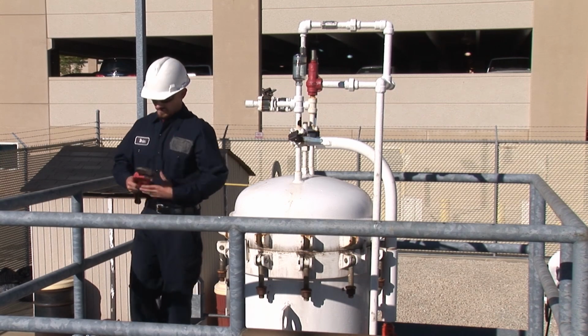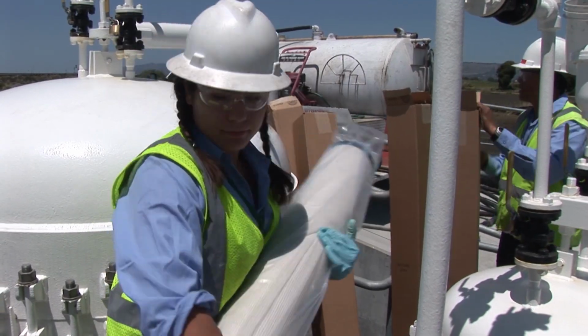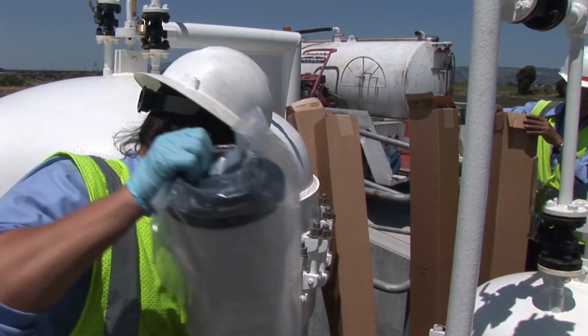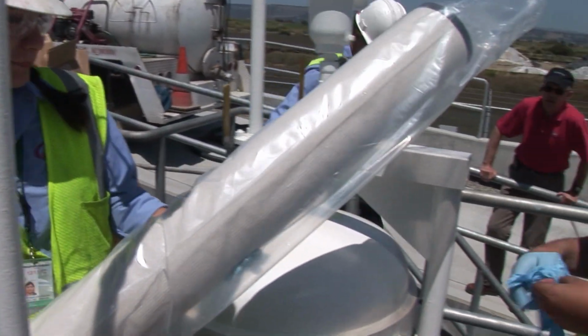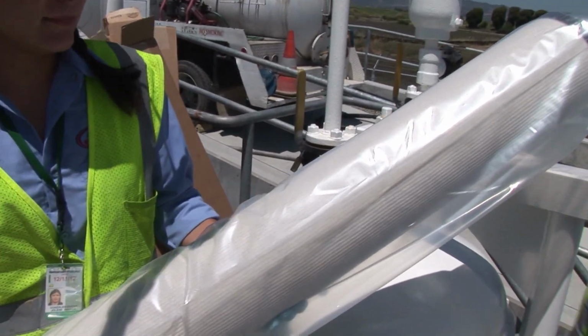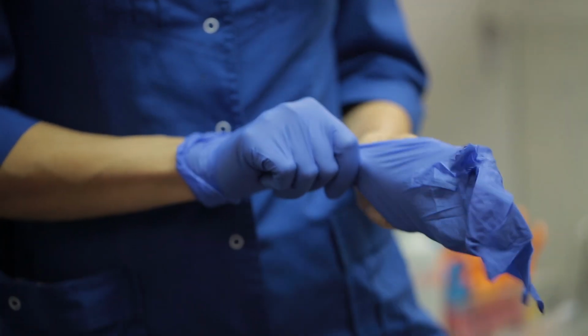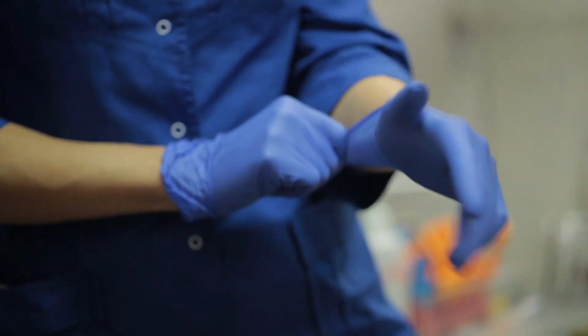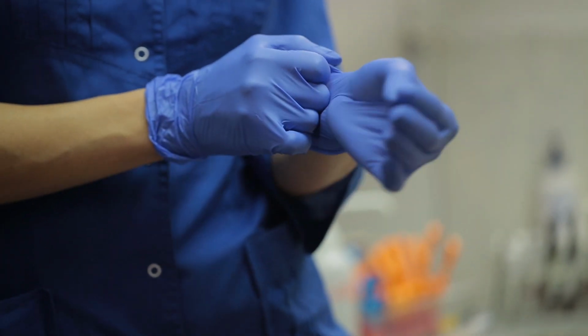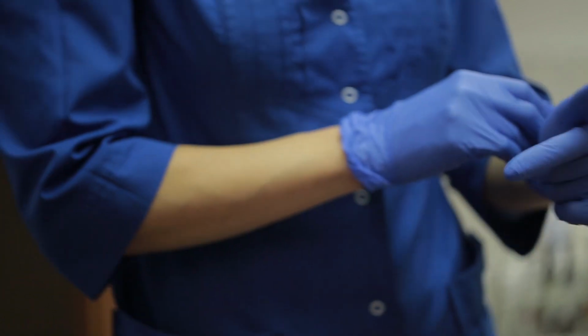Okay, let's get to the maintenance info. Begin with following your company's recommendations for use of personal protective equipment. First, handle the cartridges by the end caps without touching the filter media with your bare hands. Always wear gloves, because the natural oils on your skin will cause it to malfunction. Facet recommends disposable surgical gloves.